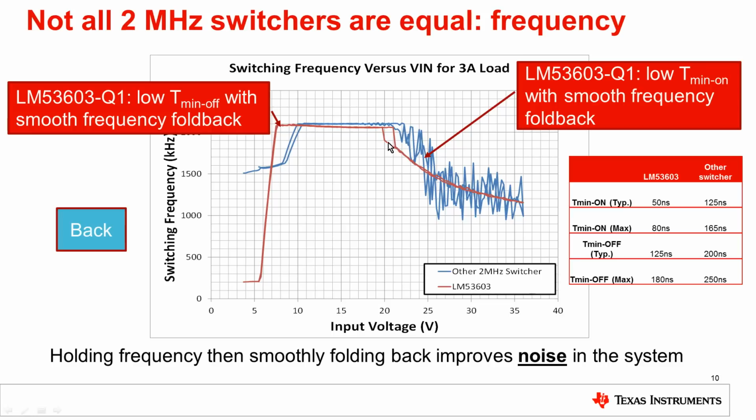Now compare that with the LM53603 performance at the high input voltage, where there is a smooth frequency fallback when the minimum on time is reached. You can see a smooth frequency fallback, and hence it offers a much better solution at higher input voltage.